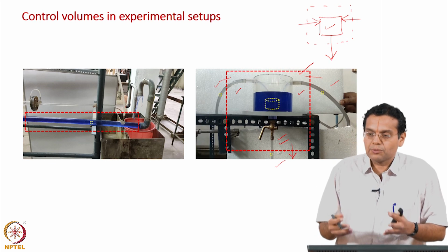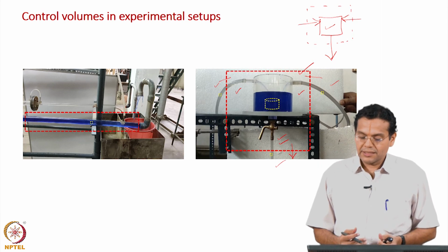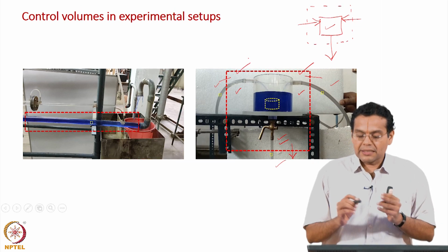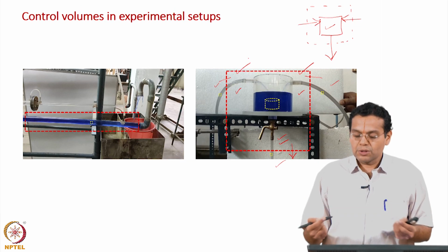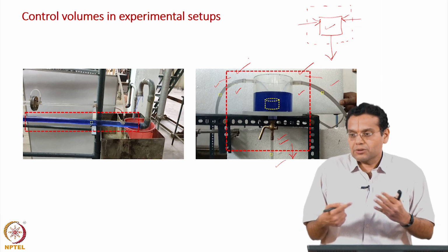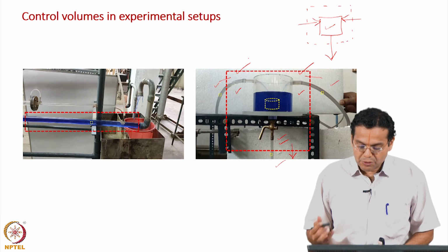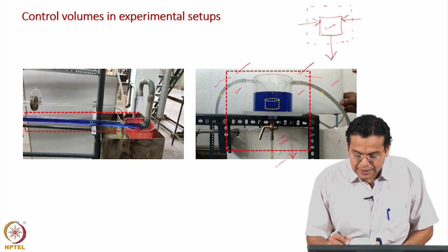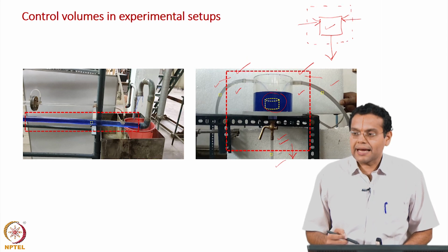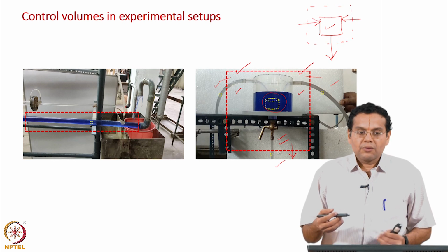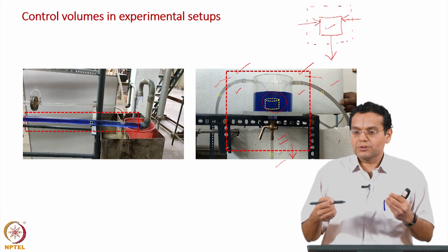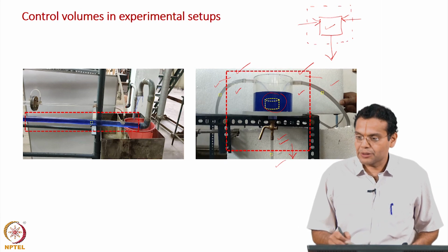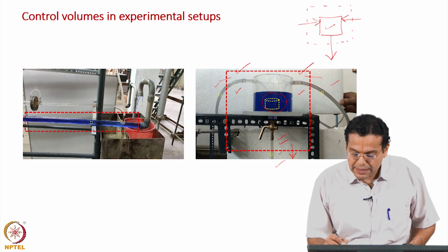Of course, I did not discuss control volume etc., it was too early to discuss, but indirectly we have taken this control volume and written a mass balance taking mass flows which cross these control surfaces. Now, I have shown few other control volumes. I can take a control volume inside the tank and analyze the fluid flowing in, flowing through, out etc. So, my control volume need not be over the entire equipment and it can be inside the equipment.